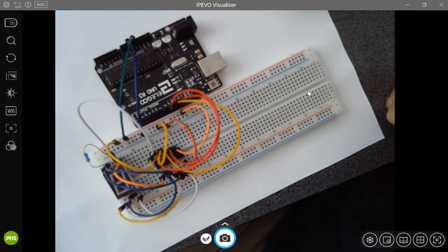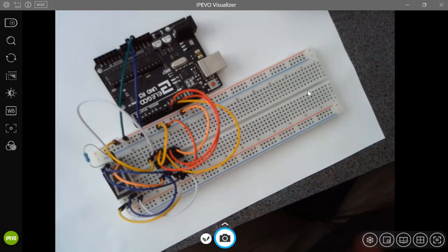So for the input voltage, it has to be at least how much? 6 volts, right? At least. But normally, if you are using a LiPo battery, 1 cell is 3.7 volts, so 2 cells will be 7.4 volts. That's the best option, actually. You just pick up a 7 point something volts, 2 batteries, put it in the cartridge, and power up your toy. Okay? Works pretty well. So 7.4 volts is a really good option.